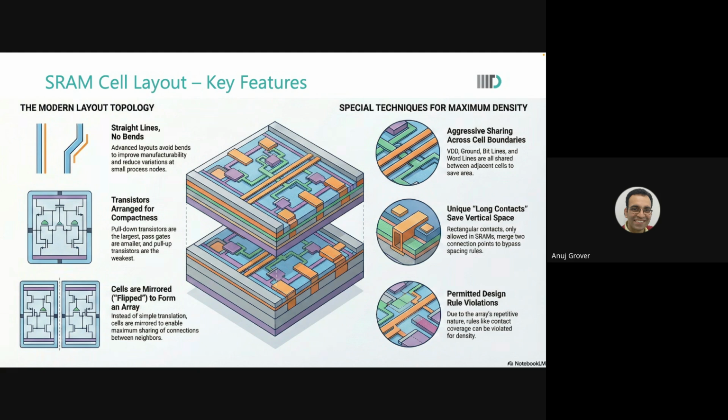So there are completely different models that we create because these devices are now very, very specific. There are specific violations that are done around them. There are specific well proximity effects, stress effects, a completely different range of things that are to be modeled in these particular devices. So when we go this dense, modeling needs to be done again.